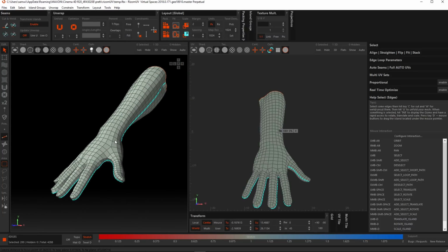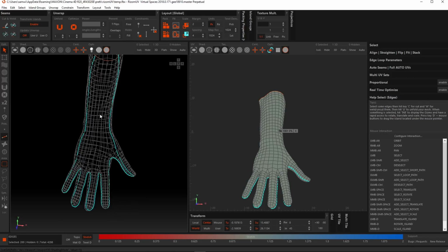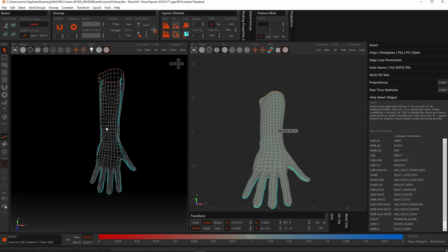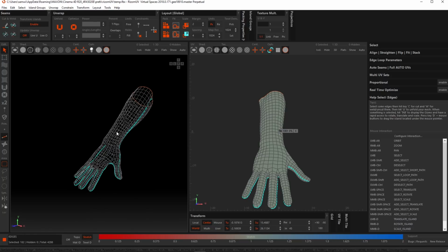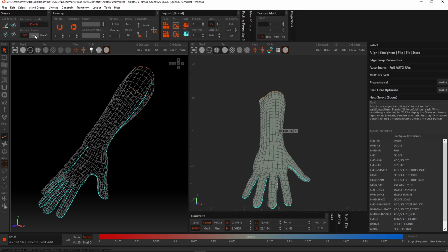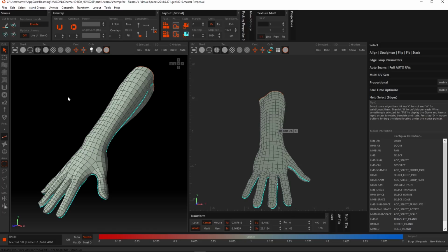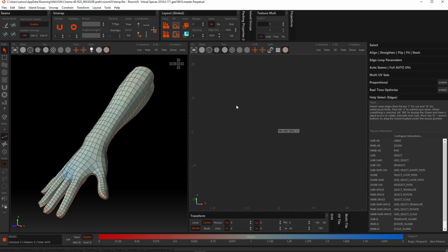And to better demonstrate my point, I'm going to go into wireframe view and unselect some of the edges. So we've got wireframe view there, and I'm going to control drag to unselect these points down to there and return to the shaded view. So let's now cut our edges. Then unfold and also frame our object in the UV view by hitting F.